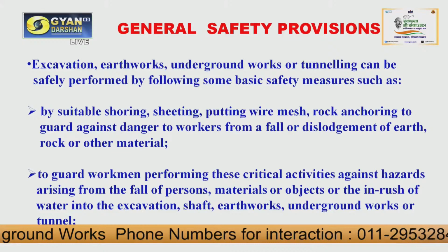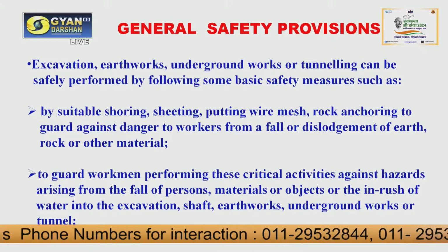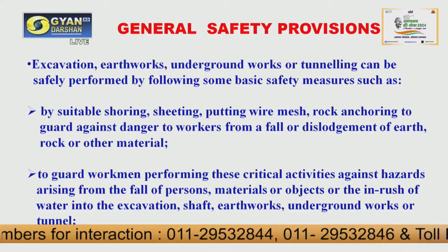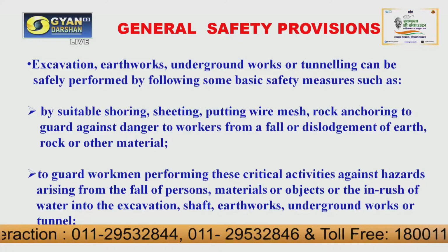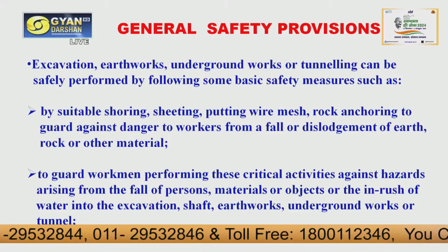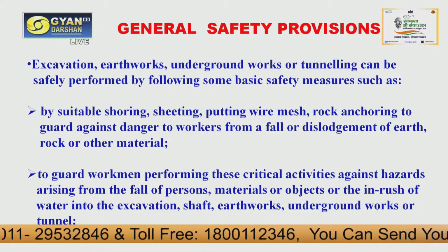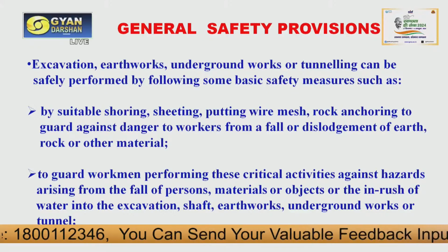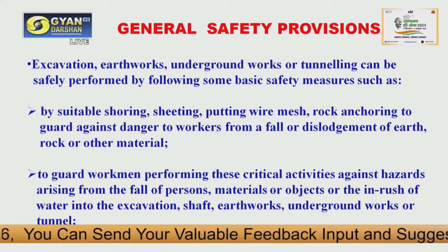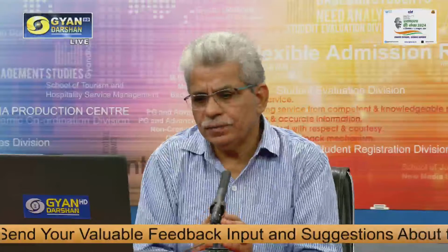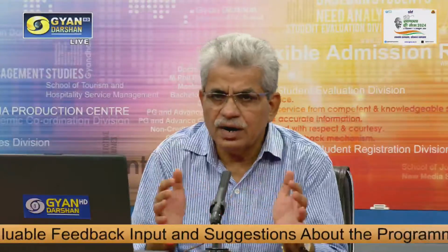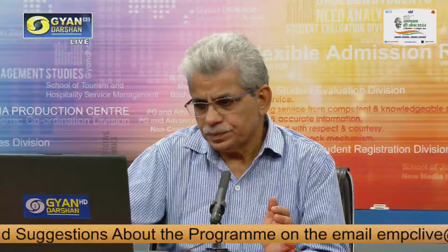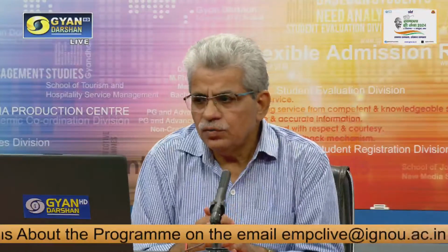We must also guard workmen performing these critical activities against hazards arising from the fall of persons, material or objects, or the inrush of water into the excavation, shaft, earthworks, underground works or tunnel. So in such cases, we should provide a guarded safe area. How can we do that?